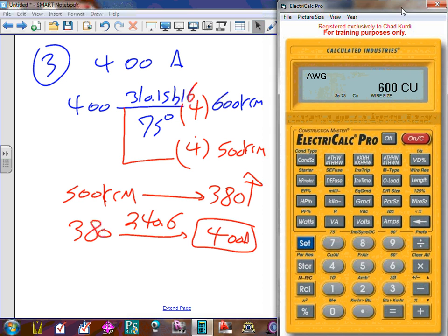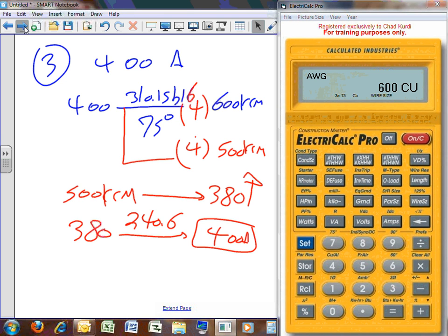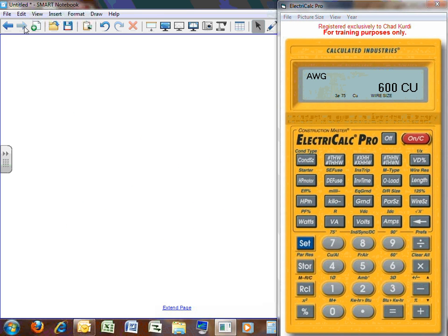We don't derate for the sake of derating. So I'm not going to tell you derate a conductor, how much amp can this conductor carry. When you derate for the size of equipment, you always start with the load. So let's go ahead and start with a couple of loads and size. First, based on no derating, and second, based on derating, and see how we come up with a different aspect. Okay, so take this. Let's do example number 5. Is that example?